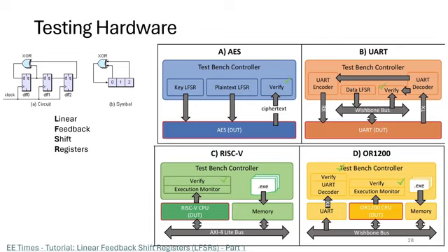So the paper itself uses 4 hardware test benches, which use multiple registers. The AES one in particular uses 128-bit registers. In that approach, you'd have to use a lot of clock cycles to iterate through every possibility of value for a 128-bit register. So go back to that definition. What other approach might be useful for eliminating suspicious registers that are very large?